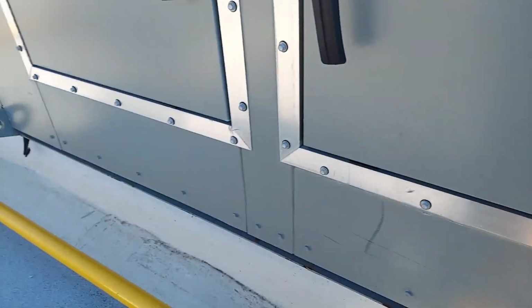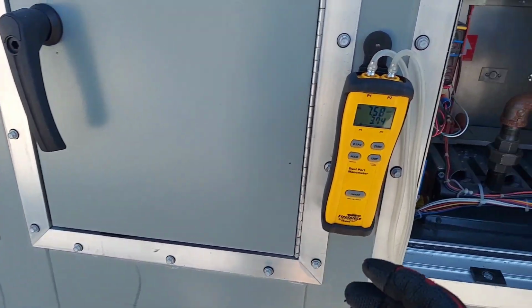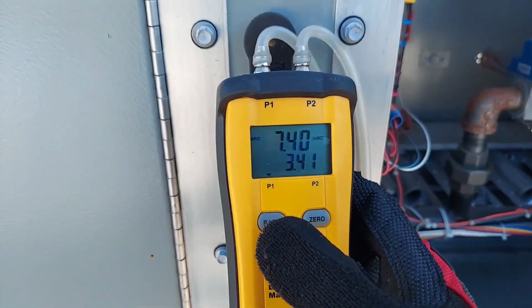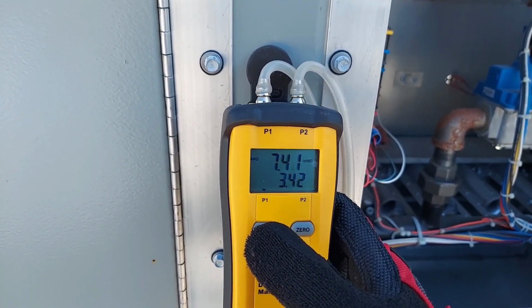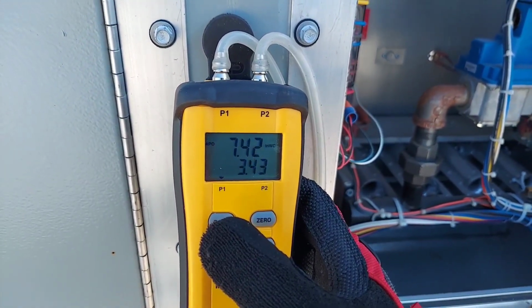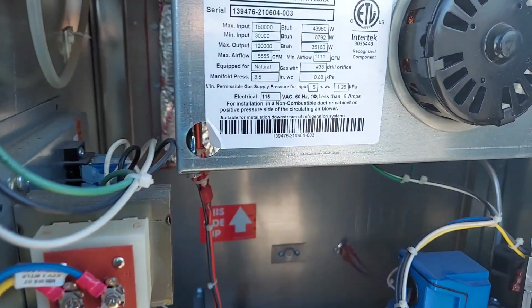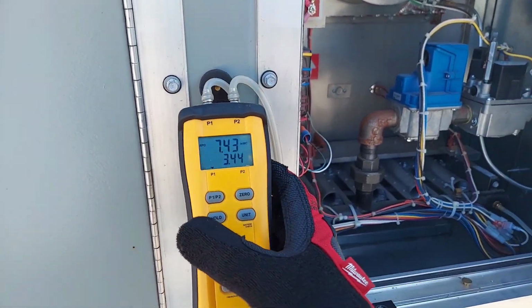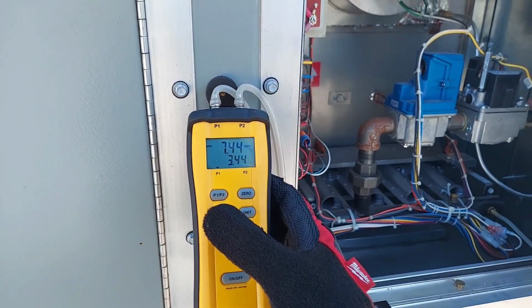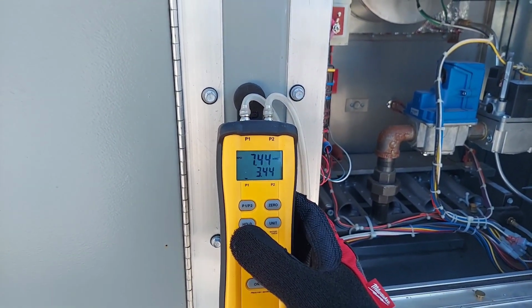So you can imagine when other units turn on and there's a high load demand, you want to have some buffer, right? You don't want to have everything set exactly, especially to the minimum. You want to go in between the highest and the lowest. So the minimum is 5, maximum is 13. I'm looking to stay anywhere in between 5 and 13, preferably on the higher end.